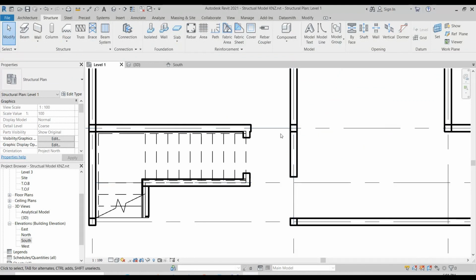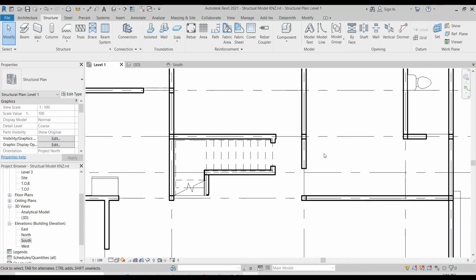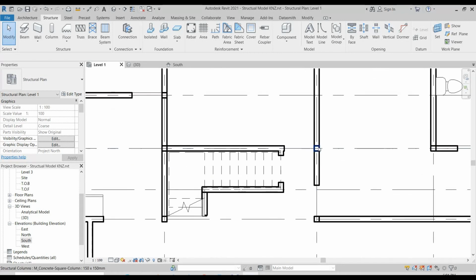So once you introduce new columns, you have to advise your architect to edit his doors, probably push them in, or you guys have to go around it. Find a way to do that. So columns here, you probably have to push his door inner this way. I was asking whether you'll be able to open it here. You'll be able to open it because there's a staircase at the top. It doesn't hit the height of the door, so it's easy to open it. Don't worry about that.